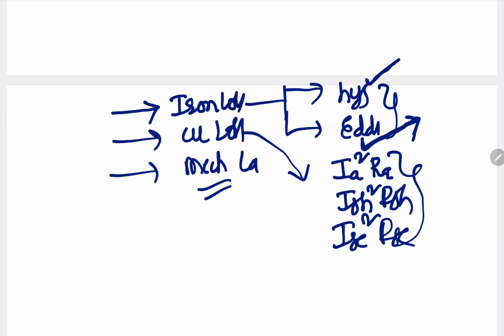Mechanical losses are of two types: frictional losses and windage losses. Due to aging, some friction gets developed at the supports, and due to that the friction losses occur. Windage loss means, due to wind friction against the armature rotation, some power is lost; that is called windage loss. And we use bearings to reduce the frictional losses.